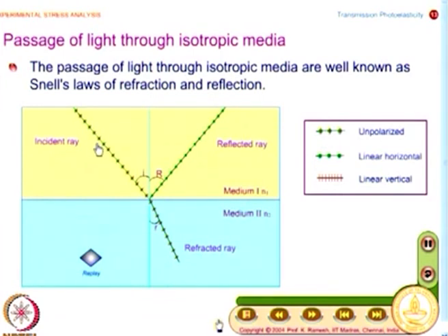This is very simple, you all know. The only thing we are going to look at is, from our viewpoint, how we look at even refractive index. You know sin i by sin r, all that you know from your understanding of physics, but we will look at it as a ratio of velocities, that is more advantageous from the photoelasticity point of view. When I look at the same concept with a different perspective, I get new insights into how this could be exploited as an experimental technique. For any interference, I need two beams, and photoelasticity comes under the category of common path interferometers, and we have to understand how two beams come.